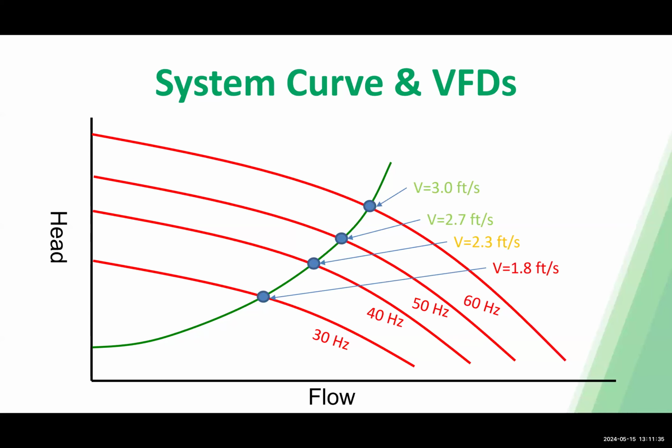So that's why you always want to take into account your system head curve, so you can determine all of your flow rates at the various frequencies or various rotational speeds for that pump at whatever speeds you want to operate at.